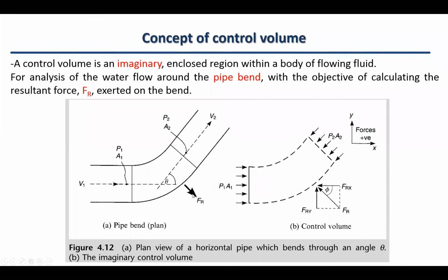So this is the momentum because of the change of the direction. As a very simple example of this one, I can give you a hose, like a plastic pipe. If it's empty, it's fine, but once you turn on the tap and the flow is running through the hose, you can see the hose is kicking. And if you turn up the volume of the flow, you can see that kicking is stronger.